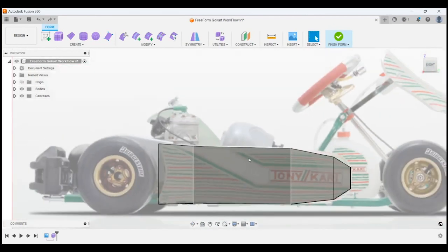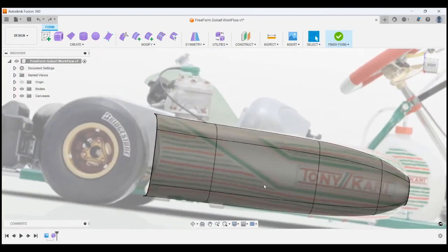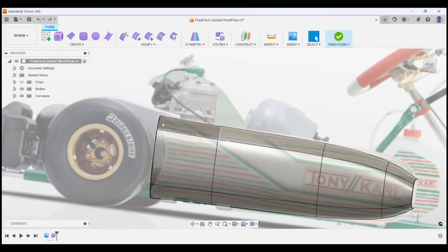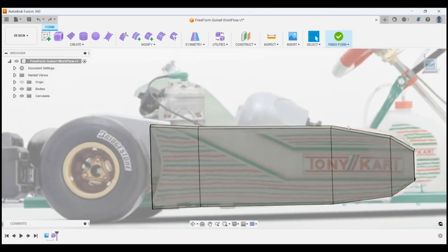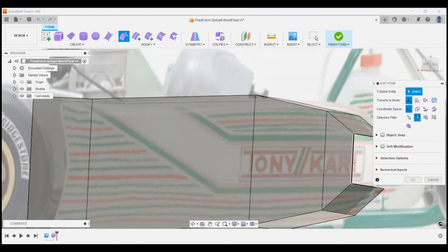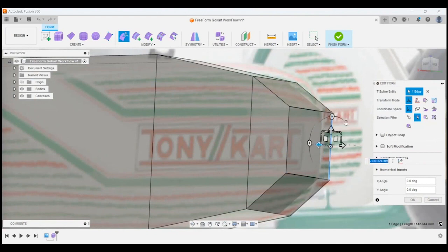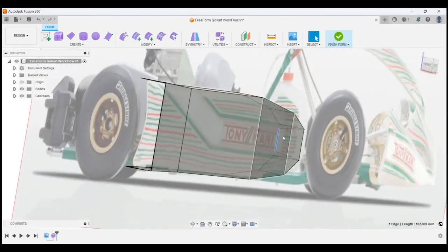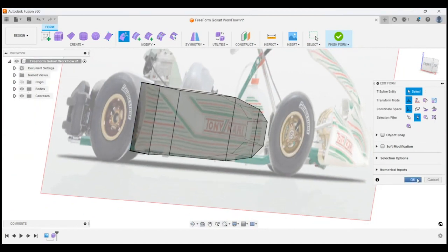So if we just go into smooth display there, we can see this is very curved. We're not matching our geometry here at the top or the bottom, and the back needs to follow the profile of the tire a bit more. So we'll start by adding in some control points. I might close off these edges first, so it'll give us a better feel for how the geometry is playing out. And just to make life easier, we'll just scale that down a bit to make the welding of the vertices easier. I'll do the same here for the back. Yeah, that's good enough.